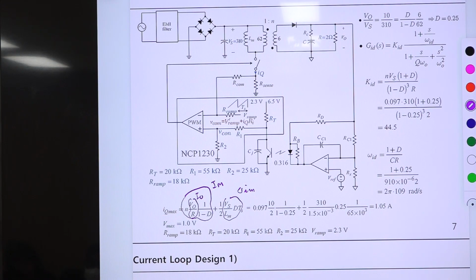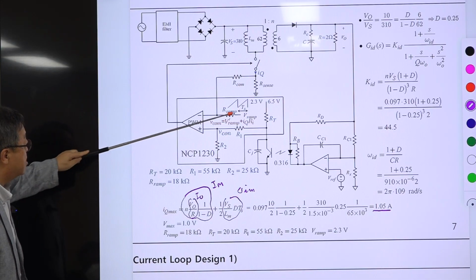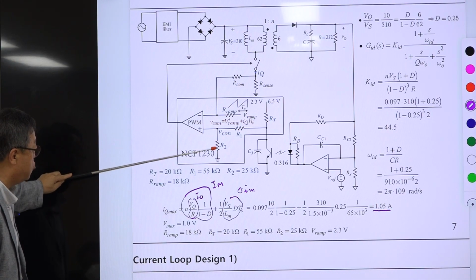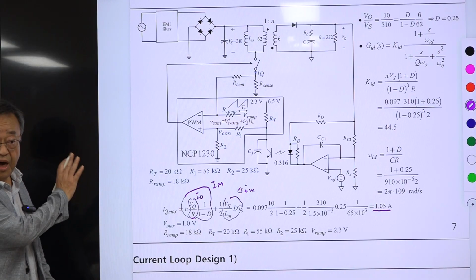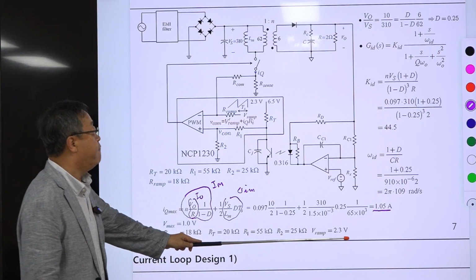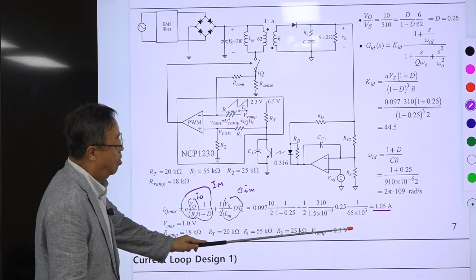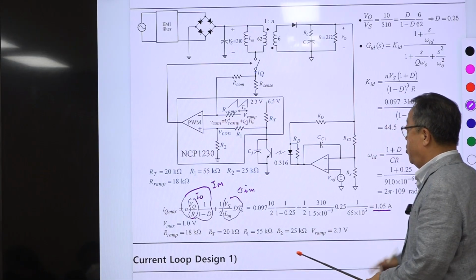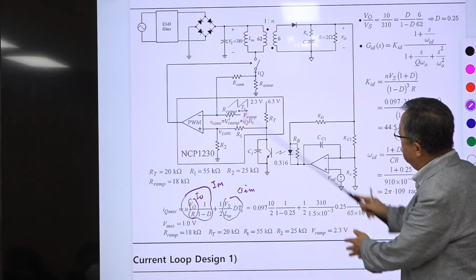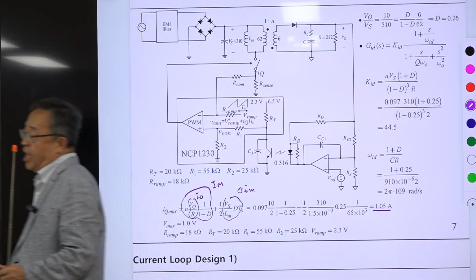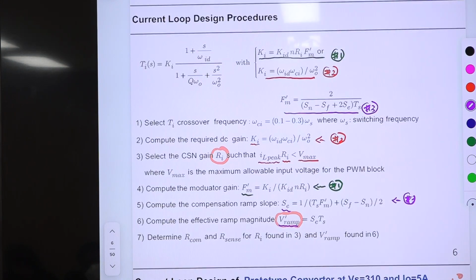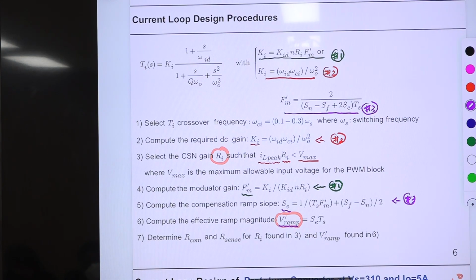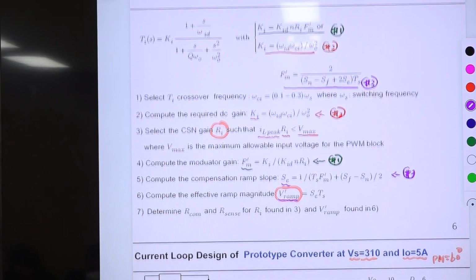So this is 1.5 amp. And this value, Rramp, and RT and R1, R2 are all determined by the IC designer, and the peak value of Vramp is fixed at 2.3 volt. So with this, we control this to have the desired value of Ri of 0.5. Oh, it's not here, no?